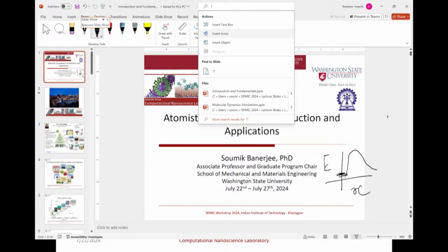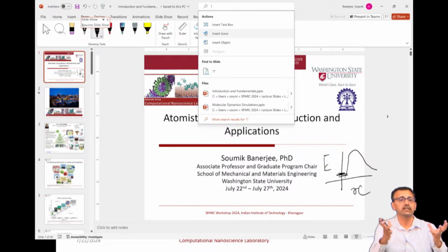So basically you're trying to go from a higher energy state to a lower energy state, but that pathway involves a saddle point or a higher energy state. So the activation energy is the energy required to overcome that barrier, and the nature of that barrier is fundamentally governed by the quantum mechanics of the interaction of that atom with its neighboring short range order atoms. That decides what the barrier is. So basically the collision between the atoms together.